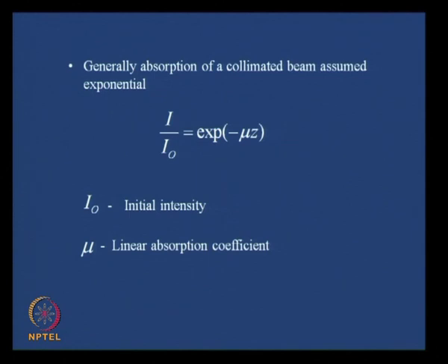Definitely this mu will depend upon the attenuating material and the source, and therefore, for two-phase flow this mu is going to vary with the composition of the two-phase mixture. And from here we can get the chordal average void fraction. From the chordal average we can get the area average by any of the three techniques. The first is to measure at different positions and obtain the area average by suitable mathematical manipulation. The other is to use a multi-beam densitometer, where the multiple beams are generated from a single source, and this is particularly useful for transient cases.